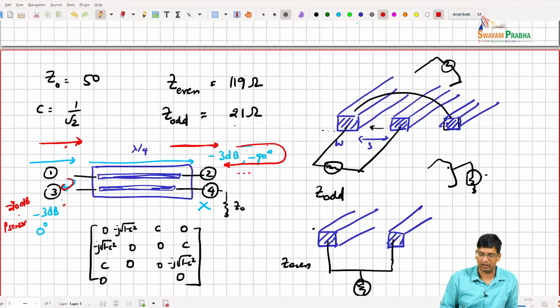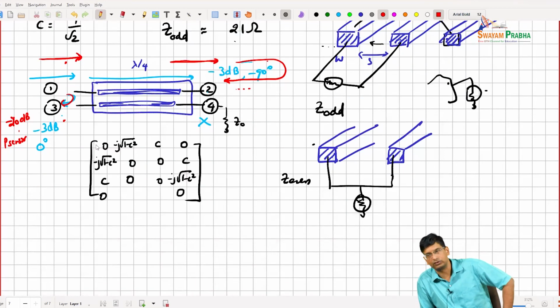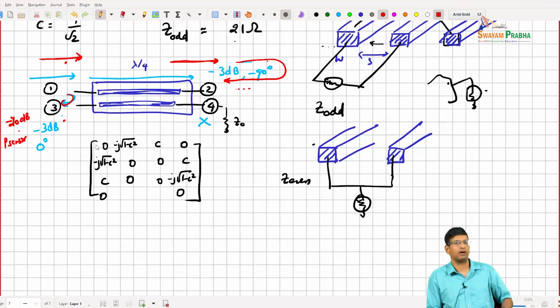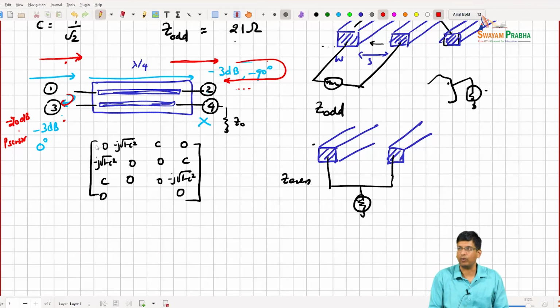So this kind of coupler is quite useful, both as a coupler where you have an unequal power split, or a coupler where you have an equal power split and you are splitting power in order to get quadrature. And it's quite a wideband coupler, right? And there are techniques to make it more wideband by using multiple sections of these, which are at different lambda over 4, right? And you can even use shorter sections which are not quite lambda over 4 and cascade them. And when you do that, you effectively build yourself a very, very wideband coupler, right?